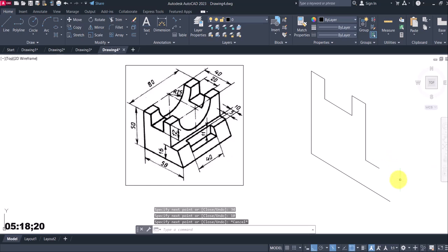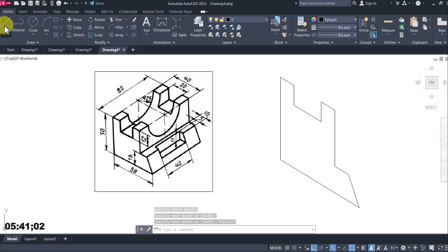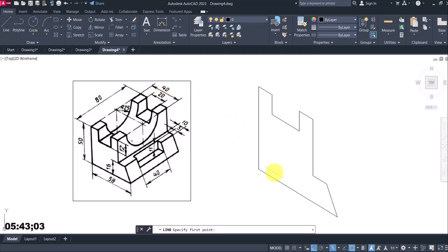So now I'm at this point. Now I'm at this line. As I said previously, this line is not in isometric direction. So for me to draw it, I have to terminate at this point, then continue from here to get to the other end of the line. Now I can connect both lines using my object snap. So that's how to get this line that is not in isometric direction. So now let me continue with my drawing.